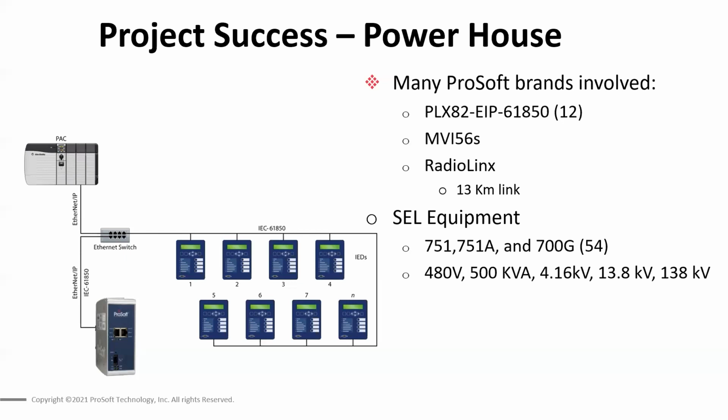So another question came through. Have you tested what is the average estimated time required to send data from the IED to ControlLogix and back to the IED by using this gateway? We did do some performance testing with the gateway module, and it was dependent on a couple of factors: the number of IO connections and the number of devices on the network.